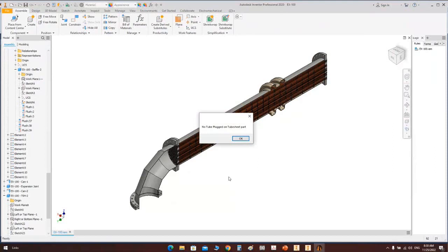Okay. You will find many tutorial videos on our channel that discuss the integration with PVElite and how you can import the Access database file in a correct way. The point is, when you export the Access database file from PVElite, you should export it in a certain format. The dimensions should be in millimeters, and the naming of elements should be unique. That's the first point. Not including any unexpected characters.